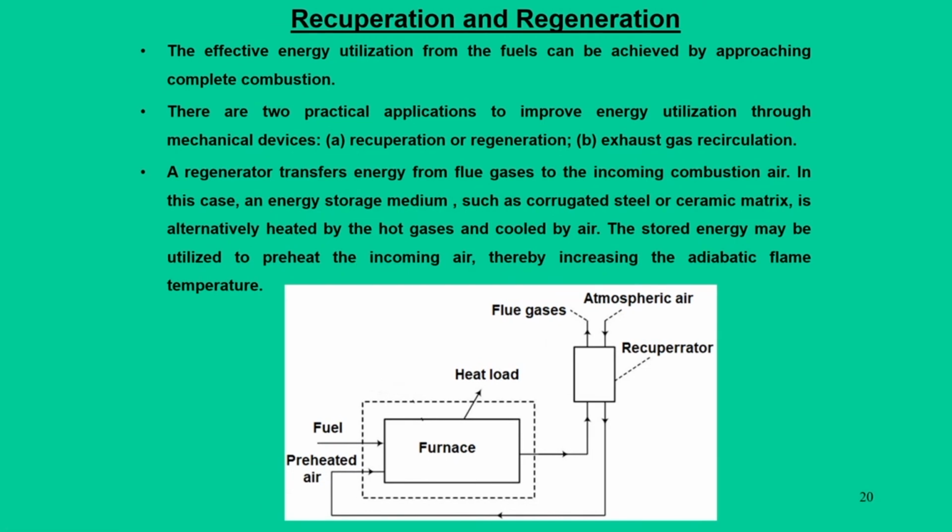Another way of looking at this, instead of a recirculator, people use a regenerator. What does it do? A regenerator transfers the energy of the flue gases to the incoming combustion air. In this case, the regenerator is considered an energy storage medium, and this storage can be in the form of a ceramic matrix, or it can be concrete, or steel, or a phase change material, it can be anything, and this stored energy is utilized whenever it is required. Either it can be used to preheat the air or it can be used for some other purposes.